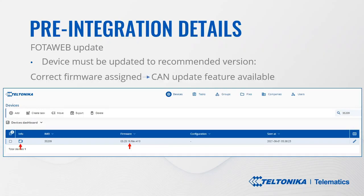Once the suitable firmware version is assigned in the device, and the device is updated to that specific version, you can see the ability to update the CAN adapter. Basically, you will see a logo of the CAN adapter, which means you can proceed with the update. To apply the update, you must create a task. This can be applied for all of the units, specific units or a single unit. When the units are selected, the next step is to create the task.